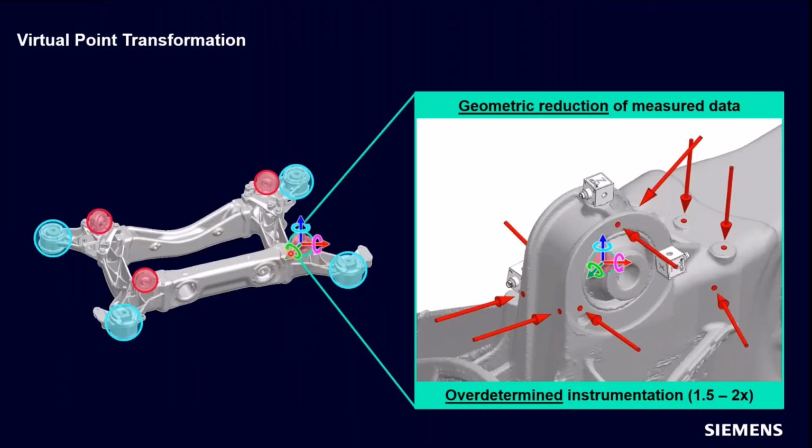The idea here is that if we have a subframe in this case and we want to characterize one of the mounts on the active side, so this is a suspension connection, we're going to need to measure some data probably at the center of that mount. And a problem there, as you can see from the instrumentation setup that I'm using here, is that it's generally impossible to measure acceleration at exactly the center of a mount or to put an impact hammer or a shaker at that center. We need an indirect way to obtain, in this case, FRF data at the center of that mount.